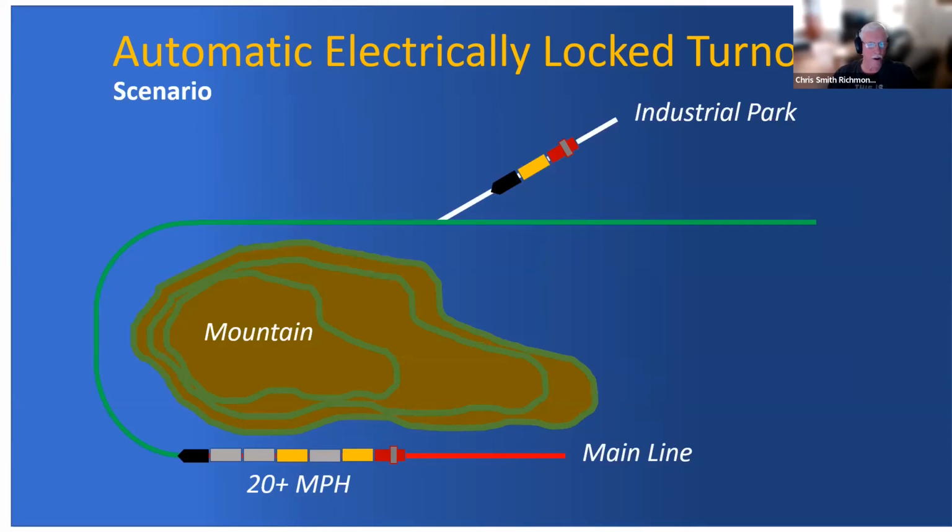So here's the scenario where the interlocking logic, the locking logic, protects the crew. It would be obvious that the crew might hear that train coming, but let's say the train is pretty far away around the mountain, and the crew can't see it or hear it. You can see where, if they're not protected and the dispatcher forgot that he had already reserved that track, they could inadvertently open those points. So the green indicates on the dispatcher screen that that track is already reserved, and the system knows that it's not going to allow that LED to come on.